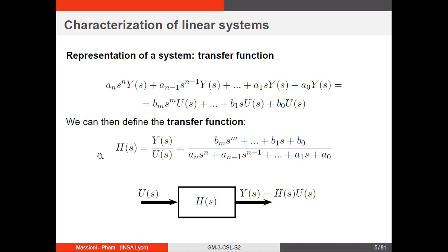And this is what we call a transfer function. So basically, if you have a signal u entering your system, u of S, you can compute the output y of S in the case of 0 initial condition. I repeat it again, in the case of 0 initial condition, simply by multiplying u of S times h of S. You see it here.